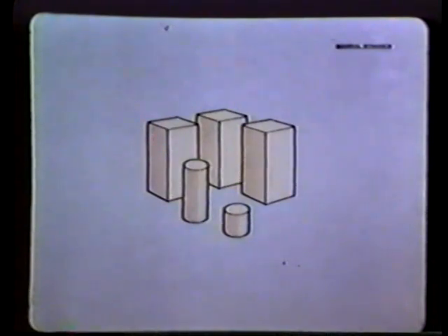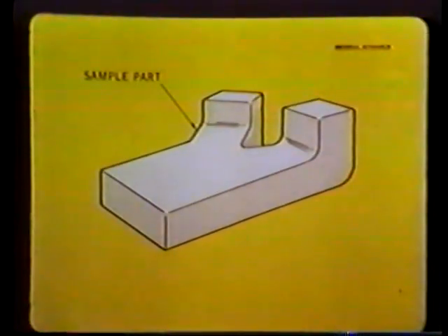If test blocks of identical material aren't available, they must at least be similar to the test specimen in sound attenuation, velocity, acoustic impedance. Sometimes, instead of using standard reference blocks, a representative sample part is selected and made into a test standard.